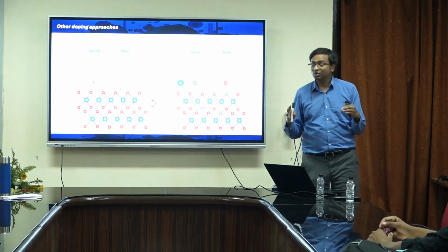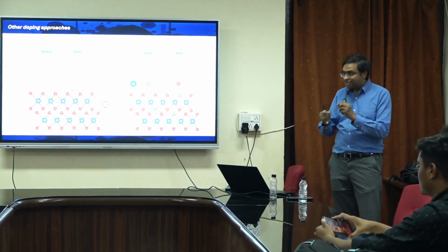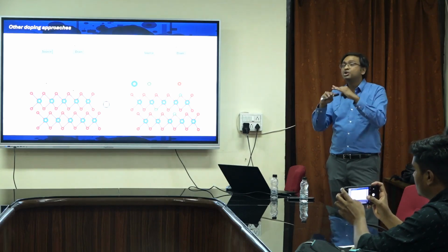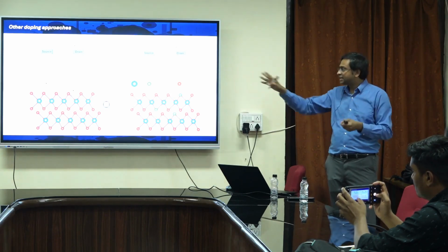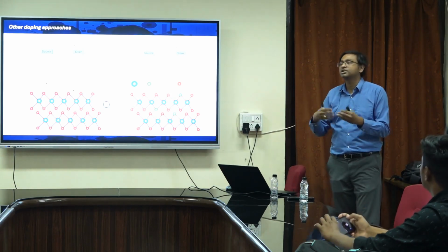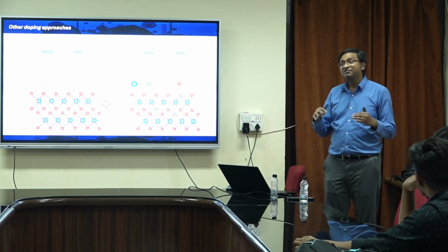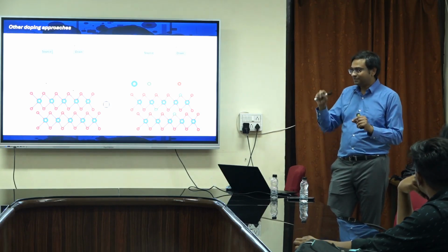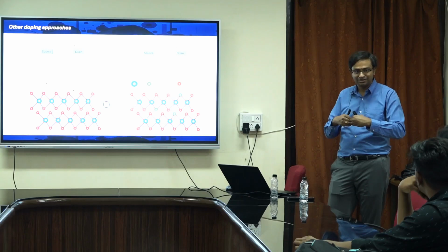This is also something mostly possible only for 2D material, where you don't have to change the atoms inside the 2D material, but you put something close to it and it does a charge transfer. That is called surface charge transfer doping because our 2D material is nothing but a surface, right? I could do that for 2D, I cannot do it for silicon because silicon is bulk. If I put something on the surface, something will happen close to the surface but nothing underneath.